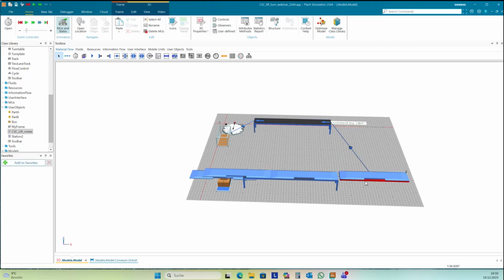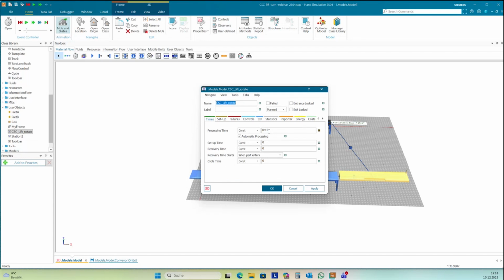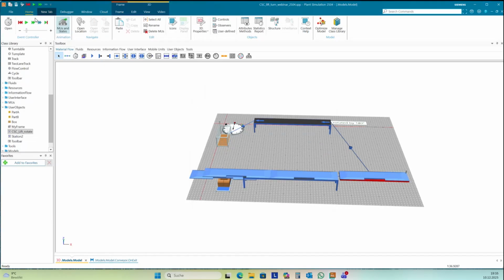Okay, remember we have this first time for transport of the part to the end of the cross-sliding car and start all the movements we have here in the processing time. We can change this maybe to 5 seconds to let it run more smoothly here. All these movements take a lot of time, and you may change this behavior.